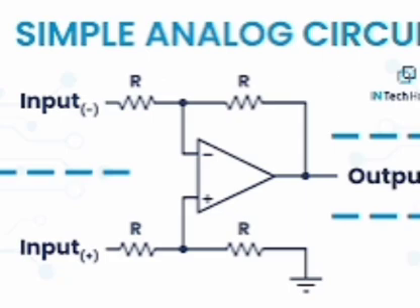Full wave bridge rectifier. For full wave bridge rectifier, bridge type, in all the formulas RS by 2 is replaced by RS and RF is replaced by 2RF. For bridge type, PIV equal to VM, TUF equal to 0.812. Conduction angle theta equal to 2 pi in ideal case, theta equal to 2 pi minus 4 sin inverse of V gamma by VM. For center tap, theta equal to pi minus 2 sin inverse of V gamma by VM. V gamma means cut-in voltage of diode.